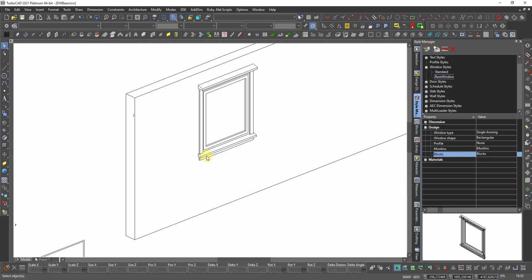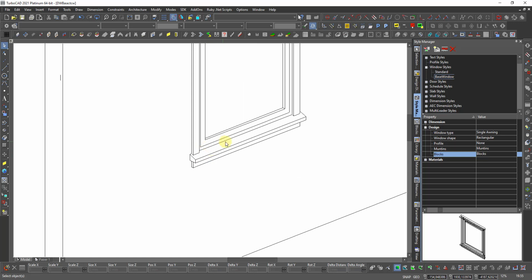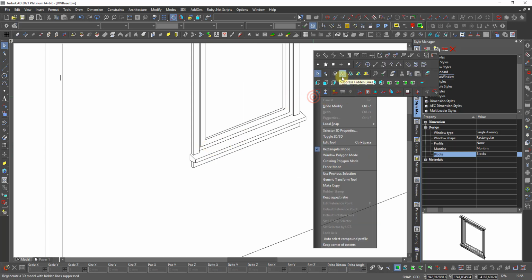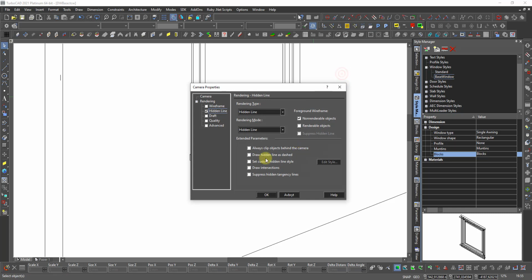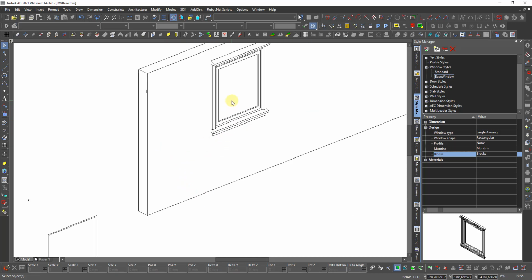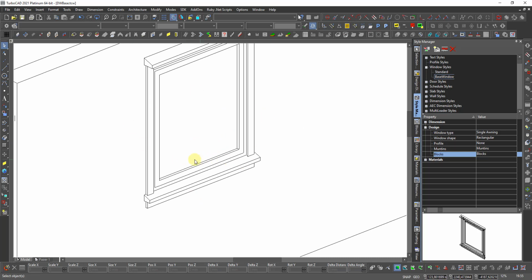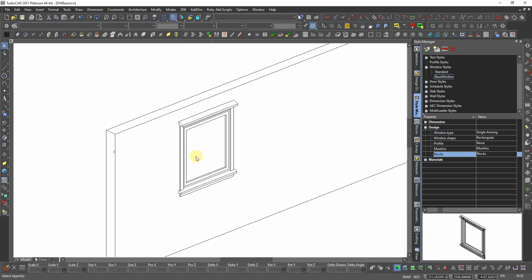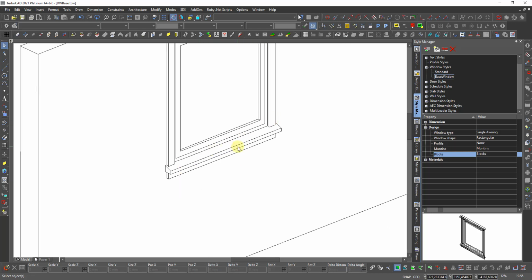But we see the line, a sharp line. In Lightwork there is a function for it. If I go there and draw intersection, if I check that one, even if they are melted together, this way we stand 1 centimeter inside, it will draw the line there. But it will do that on everything in the drawing. And when you have a house where there is 1000 of this, then the render time goes up. So I prefer it like this, instead of cheating with this extra function.